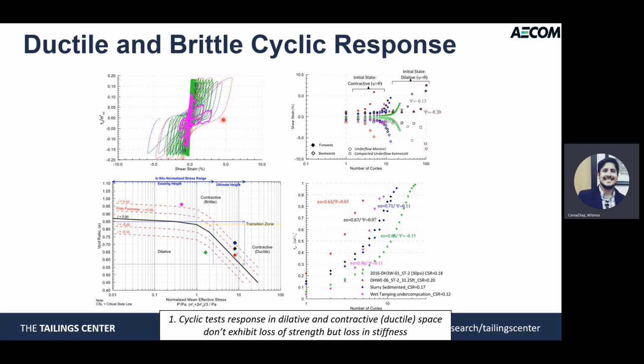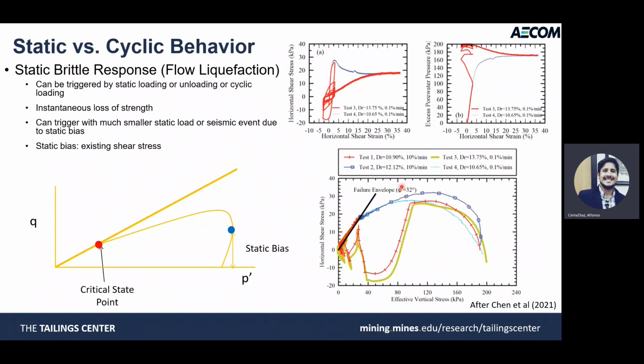Looking at aspects that are secondary but still important is multidirectional loading. These are some tests performed for Ottawa sand that Bomic performed in 2018. What you see is that if you include the other direction of movement on top of the unidirectional one, to make the stress-strain or strain path circular or figure 8, you will have more tendency for compaction. Therefore, you may generate more pore pressures under undrained loading or more compaction in drained loading.